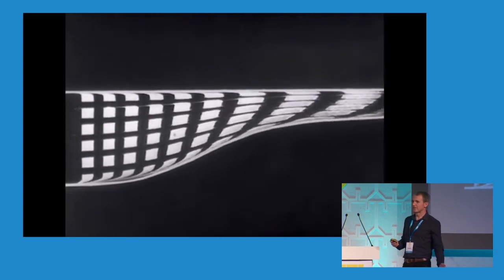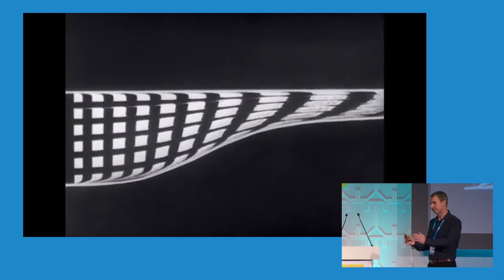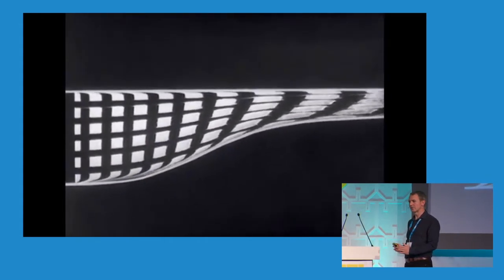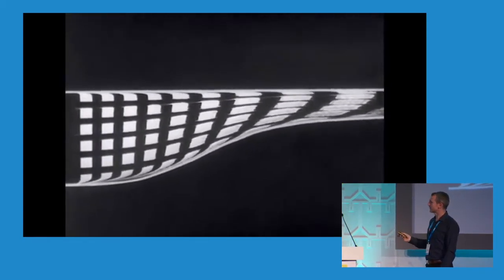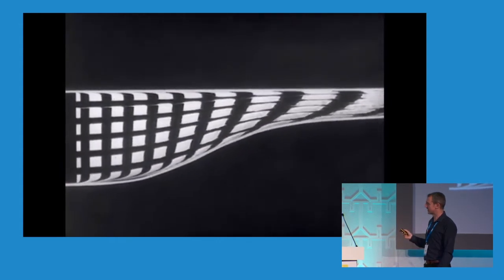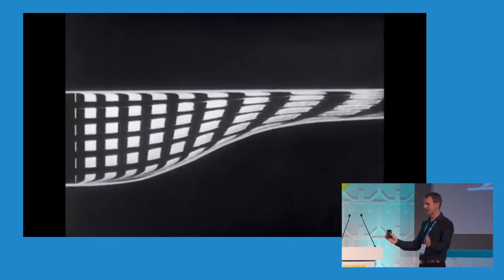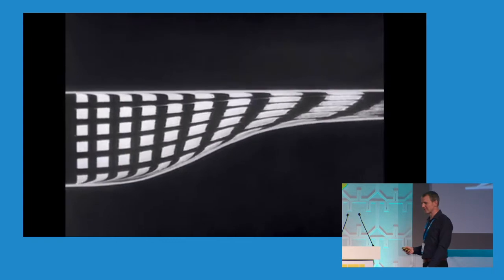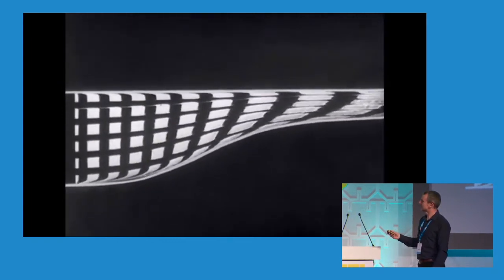So we've seen how to manage flow around corners. We've seen what happens when you restrict flow conditions. But what happens when sooner or later you've got to try and expand that flow back out into a bigger space again? Well, this is where it gets really interesting, in that there's a strange thing that happens when you expand flow and you go beyond a 7-degree angle, which is the magic number. All CFD engineers will have that in their head. And you get separation of the flow.